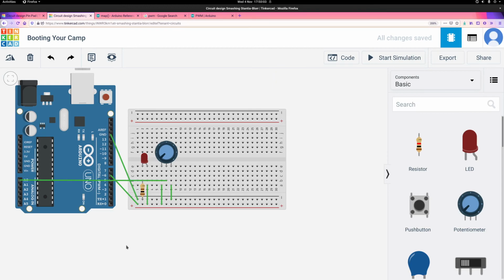Stellar. That's actually all we need to do to change our... Oh, not quite all we need to do to change our circuit. Here, we're currently turning on and off the entire power to the board, which we probably don't want to be doing because that's affecting our potentiometer as well. We just want this to be continuous power now, and we'll just turn on and off the LED. So to do that, we'll change the way this circuit is a little bit.